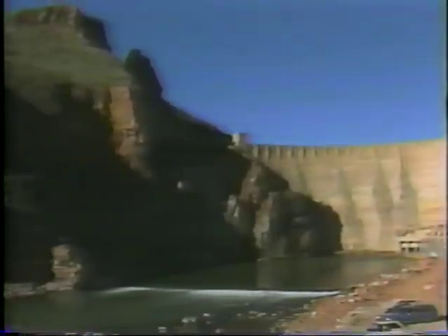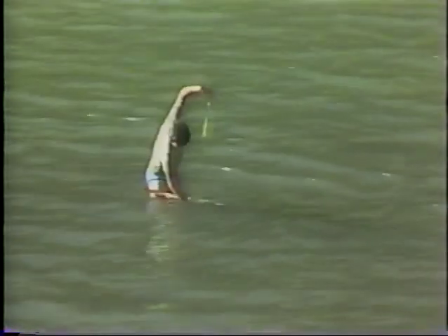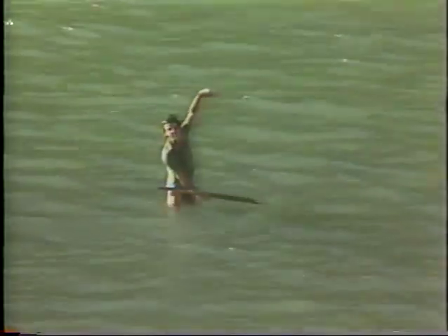Believe it or not, if you have nothing more than a stick, a tape measure, and a stopwatch, you can measure the flow rate of that dam. The first thing you've got to do is determine the average depth of the water. You can do that directly like this. So this water's about this deep.